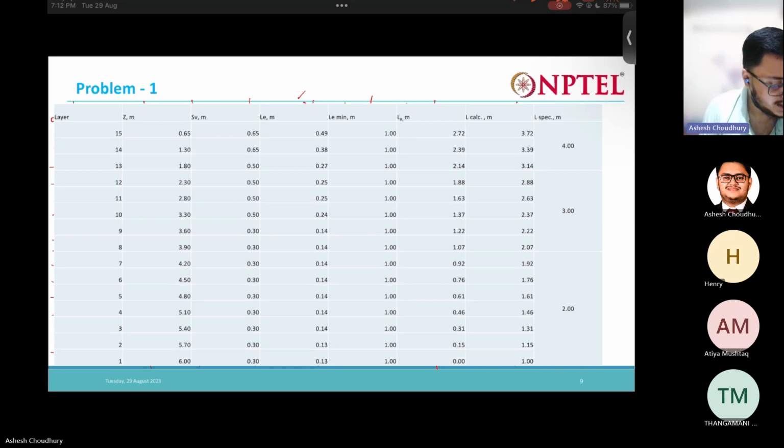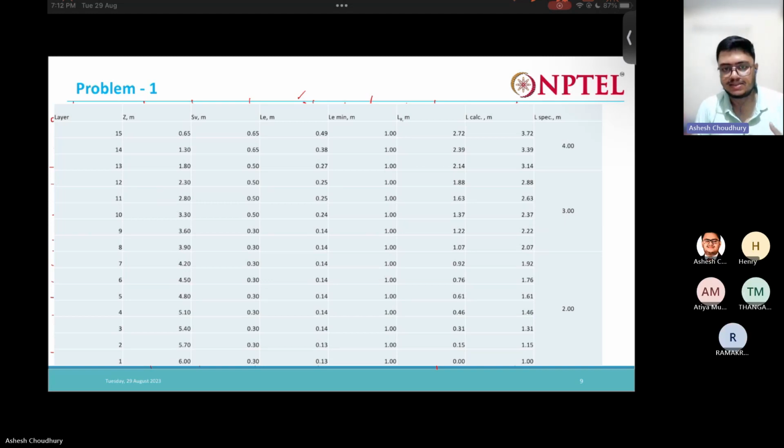Now what we need to do is the stability checks, the external stability. The internal stability criteria was already satisfied, right? We already did all the solution by satisfying the internal stability criteria, that is the rupture criteria and the pull-out criteria. Now we will be doing the final external stability checks. If you remember, what were those? Sliding, overturning, and bearing capacity. And also the fourth check is there, that is the slip circle failure.